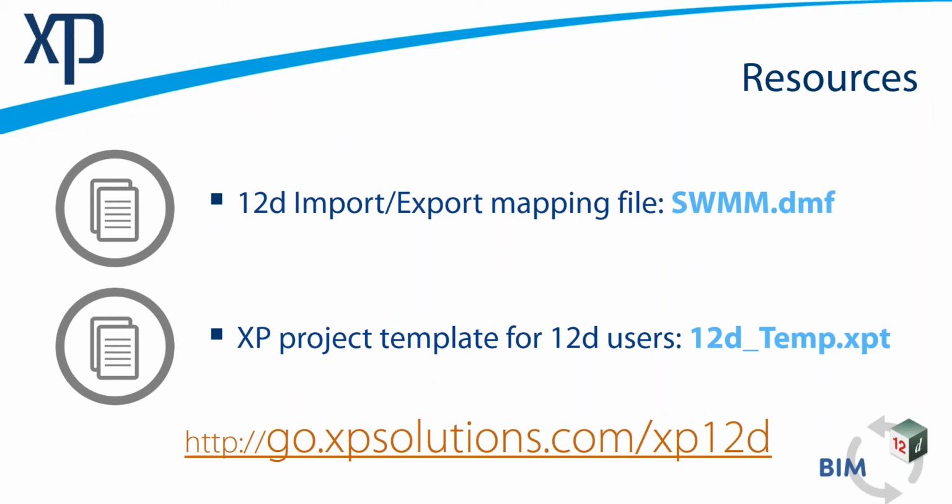Yes, that's a good point, Rob. As we do build those ones, we'll make them available as well, so users can access those for different types of hydrology and inlet pits and whatever else is needed. The other one is the 12D template, so that's how I've read in all the pits and rainfall and data that Rob sent me. And that one's just when you create a new file in XP, you use a template rather than a blank file.